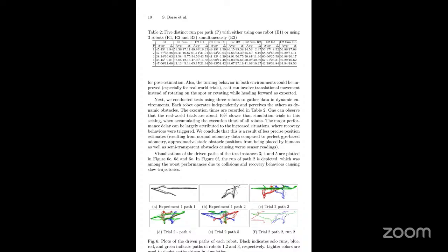Odometry error: in simulation, they used GPS-based odometry, but the real robot used encoder and IMU, so the position estimate was not accurate.